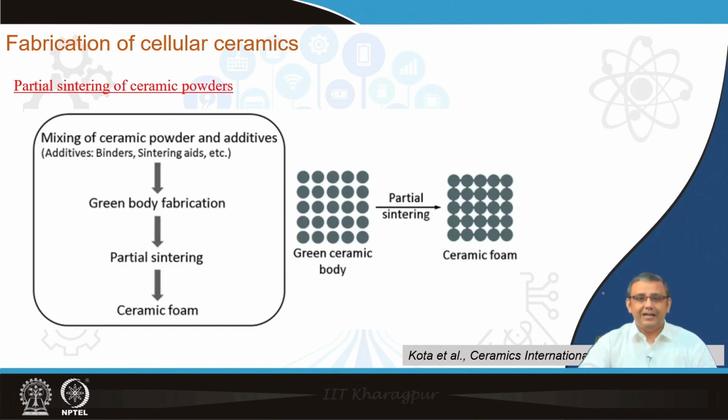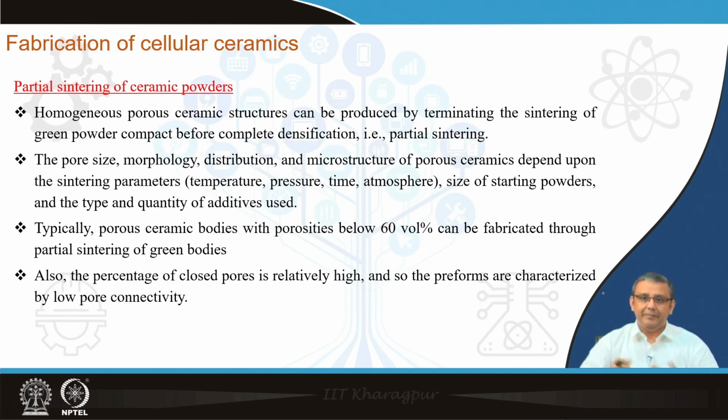So, this process has the advantage that it is very simple, and also very cost effective because you do not need very high temperatures or very long holding times. But the drawback is that because you are not fully sintering the particles, the interparticle bonding is not that strong, and that is the reason these porous ceramics after partial sintering may lack in mechanical properties.